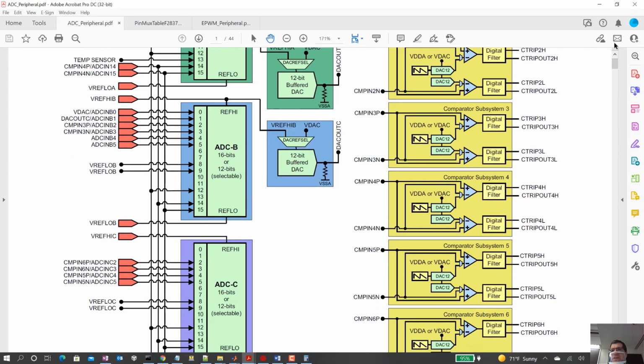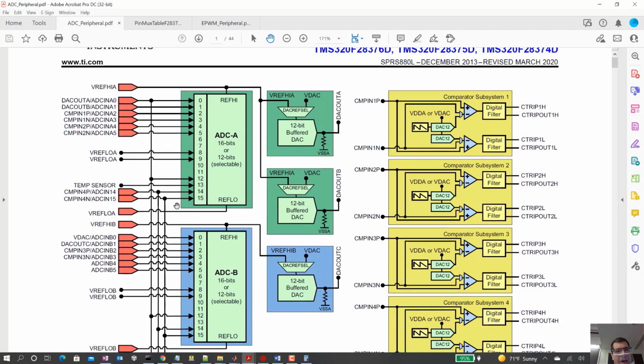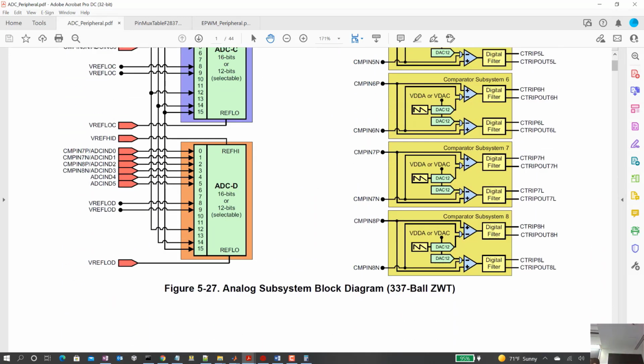And then also there's these other pins called, again, we're not going to be using these. Where are they at? Yeah, it's just called ADCIN 14 and 15. Notice how these are called ADCIN A1. So in other words, these pins are just for ADC-A, except for this silly A0. But then this 14 and 15 are for all the ADCs. Great question why they have those. I don't know if they did that for calibration reasons. I'm not sure exactly, but they've chosen that.